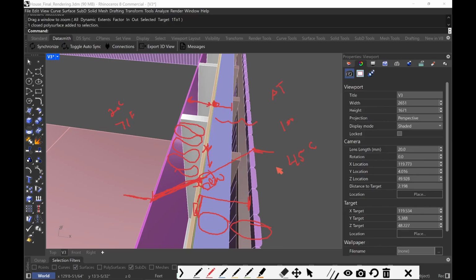If you did not have exterior insulation, then the location of your vapor profile might change depending on your wall construction. If you had zero exterior rigid insulation, in a cold climate or hot climate, most likely your vapor profile is going to change to the interior face because that's where most of the change of temperature is going to happen.